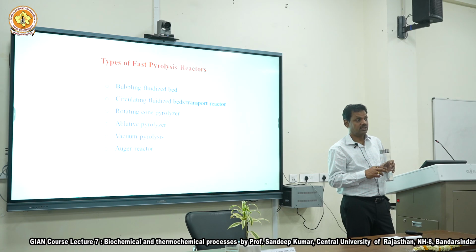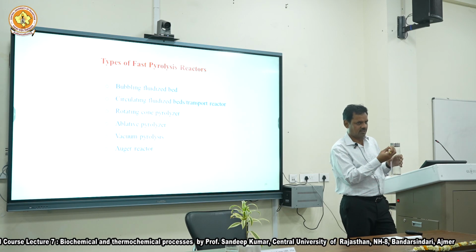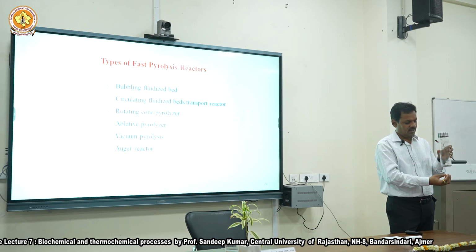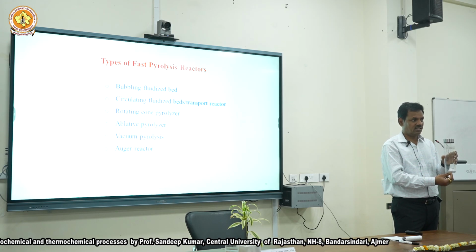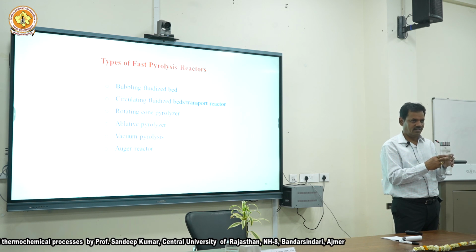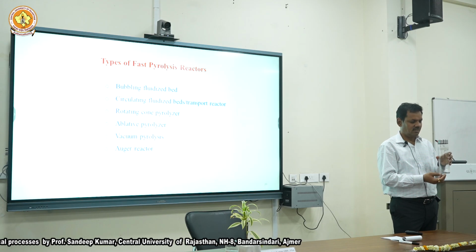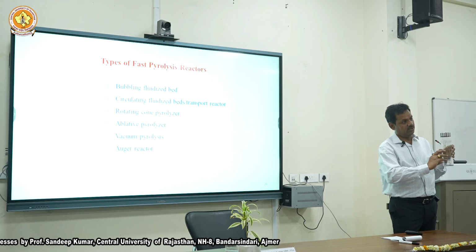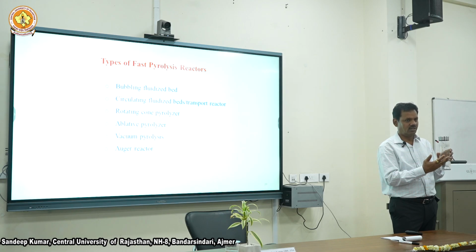So again, a whole industry is called fluidization. So you put sawdust in this, and pass nitrogen or any gas. In pyrolysis, you don't want to pass oxygen or air, because pyrolysis is done in the absence of oxygen. You pass inert gas, and you have filled it with dust, sawdust, very fine biomass.